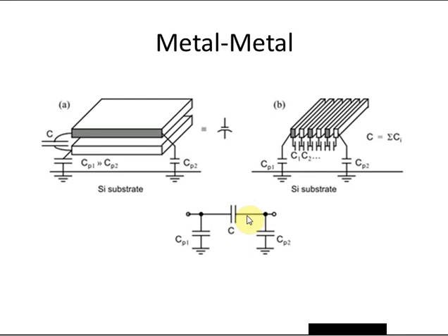This terminal here, for example, might be not necessarily connected to a ground potential. It could be connected to a supply voltage, could be connected to the virtual ground terminal of an op amp. Again, similar advantages apply since that node is not going to be moving up and down very much. It might be okay that it has a higher parasitic capacitance to ground.